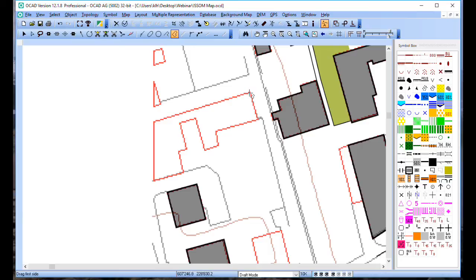For example, this building here, I choose also the longest side, but I make it too long here. Then I go on drawing. Now on this side, I can just insert two vertices with the Ctrl-Shift key and delete these two vertices with the Control key. So the rest of the building is well in a rectangular angle.